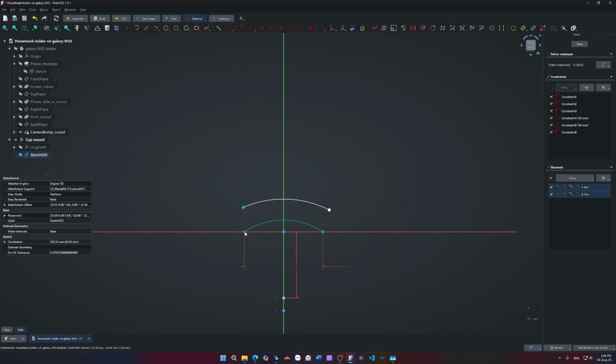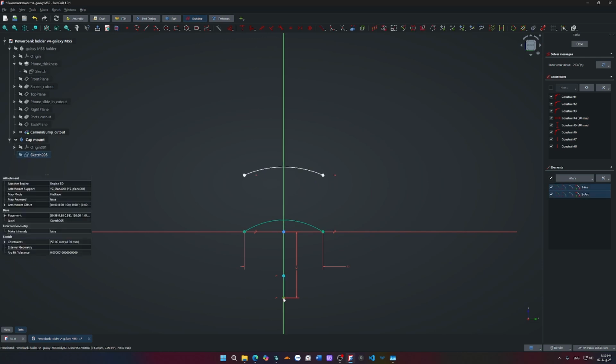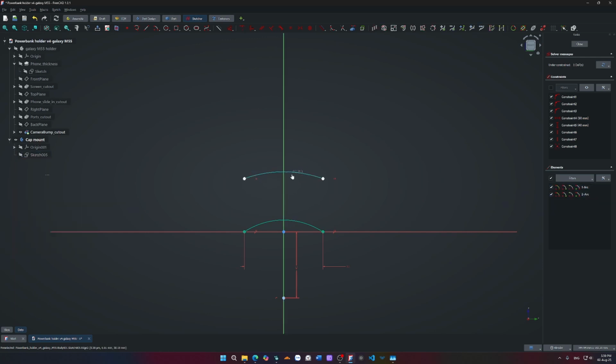This should be a vertical V, have vertical constraint and on top of each other. Very nice. And I will need to fix this point. Should I make it coincident to the old arc? Alright. Yep, now it has the same, well, not the same to be honest, but